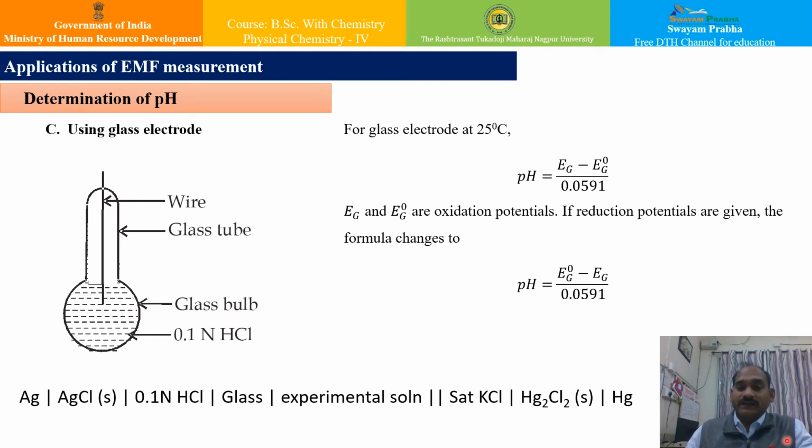Now I can determine the pH of a solution using a glass electrode as well. Basically, commercial pH meters make use of a glass electrode and a standard calomel electrode assembly to measure the pH. You must have seen the single electrode many times that comes along with a standard potentiometer or pH meter. Now, this glass electrode is a special type of electrode called an ion selective electrode.